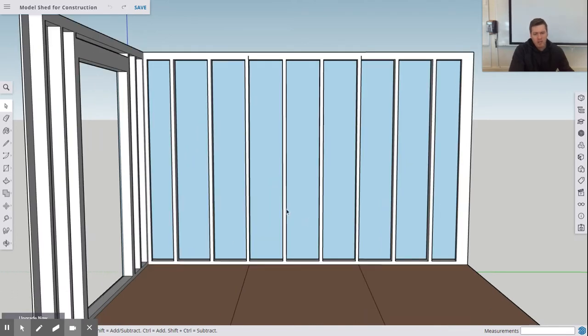Now I want to select the entire back wall. You have to be careful about the direction you select. For example, if I start from the top left-hand corner and select down like this, it doesn't select everything that I want. It only selects the majority of the items that are in the selection window. However, if I select from the bottom corner up like this, it selects anything that is in the selection window. If I select top down, once again, it only selects the items that are full instances. So if I carefully select this, hopefully it only selects the solid features.